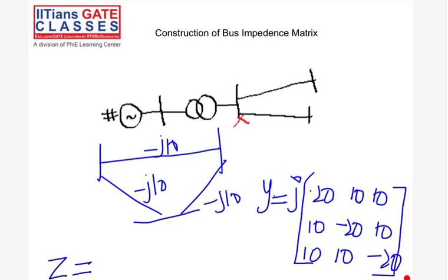In that case, we form the Z bus with a Z bus building algorithm by taking one of the buses as reference. When forming the Y bus, the reference is actually ground, so instead we take one of the other buses as reference and then build the network.